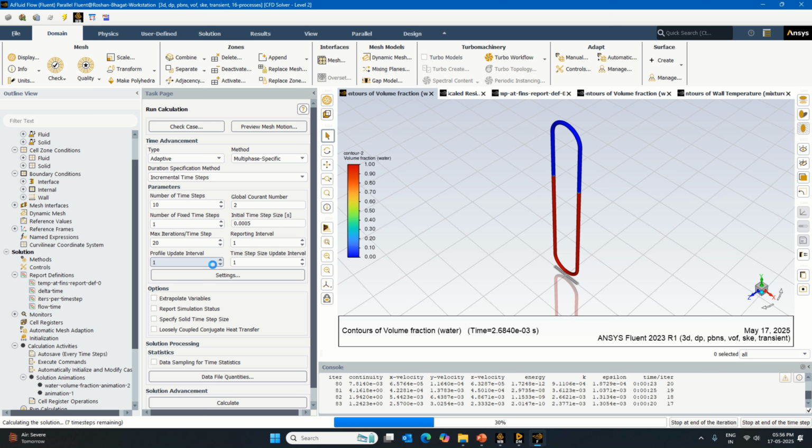Again, predicting this error to occur is very difficult. There may be chances you run the iteration for 1 lakh and the error may occur in between, or sometimes it may also not happen. So that's why it is very important to select the proper mesh size, and whatever initial time step size you are selecting. So this is also a very important task.